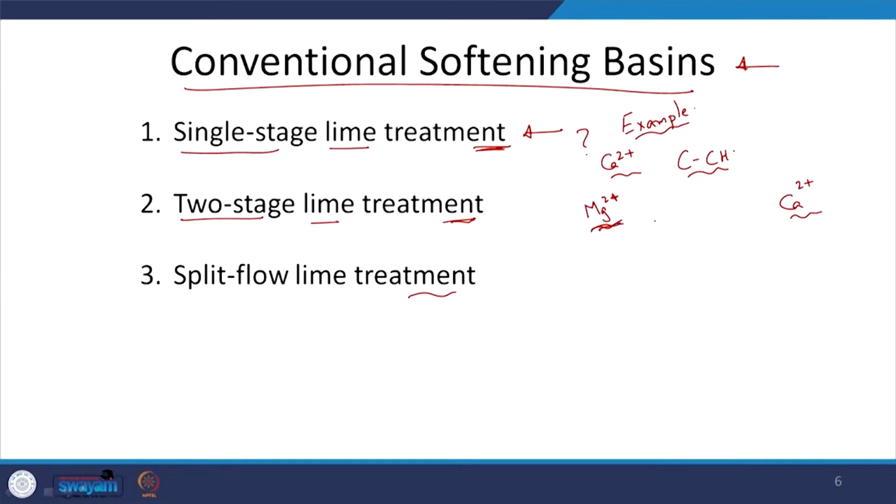So for that you will need to add the relevant soda, or CO3 2-, to precipitate out your calcium, right? To precipitate out Mg2+, you will raise the pH by adding Ca(OH)2. Yes, and if there is not enough carbonate in the system, the Ca2+ will now add to the hardness. You are replacing Mg2+ hardness with Ca2+, especially if there is no carbonate in the system. So then you are going to add a source of CO3 2-, right? So that's the relevant aspect. So we will look at how to go about it.